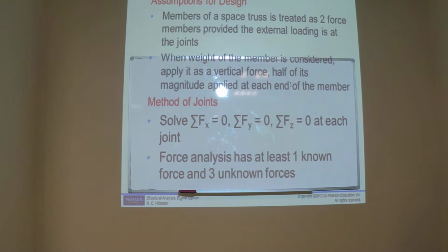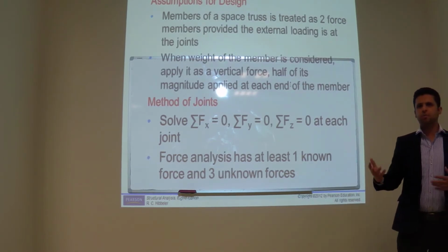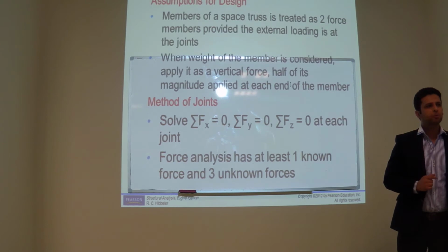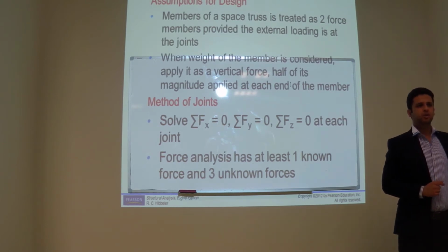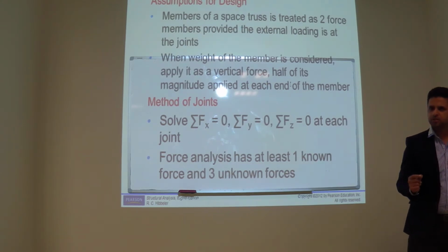Okay, now, well, these are the assumptions for design. And once you assume anything in a design process, you have to apply the same concept during the construction. Keep in your mind. For example, you are assuming a roller support for some structure, for a beam. Then you have to provide the roller support when you make that beam. Do you understand this point? Yes. If you don't do that, what will happen?